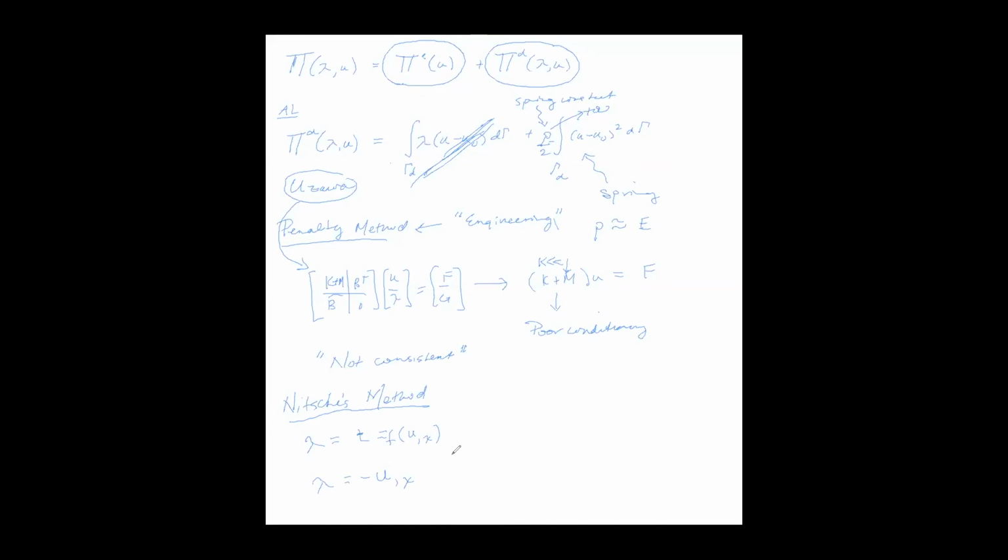You have this general framework, augmented Lagrangian, but this whole problem comes from conservation of energy, so you can identify lambda with an actual physical quantity, the traction. And we know how to write down the traction. It's just the derivative of the displacement, with some material parameters that give you the stress dotted with the normal.